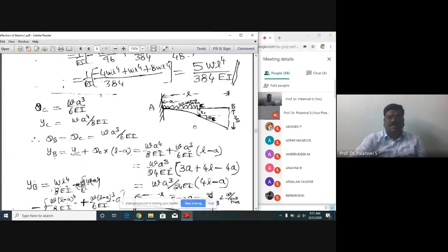So here there's a cantilever beam. Now we are seeing another case, subject to UDL at a distance a from the fixed end. Please see here, the beam bends up to under the UDL. Under the UDL there is a bending action. Thereafter, since there is no load acting here, the beam is a straight line. It will not bend because there is no bending moment thereafter. Now, how to deal with this? Say point A, point B, and point C, where the UDL ends.